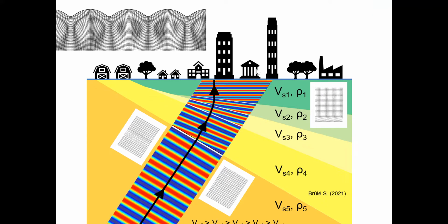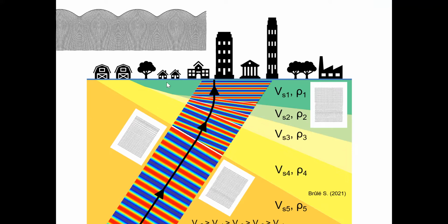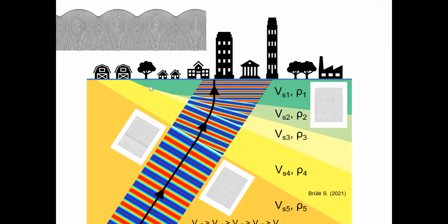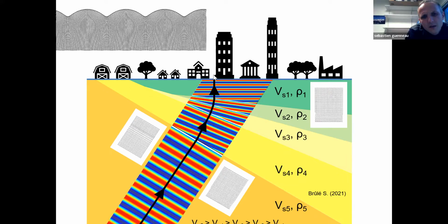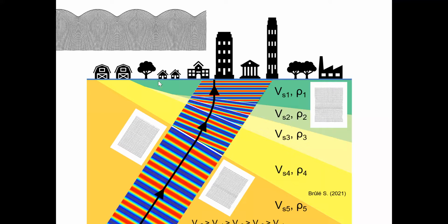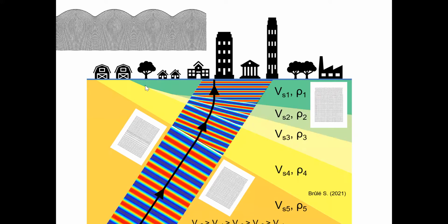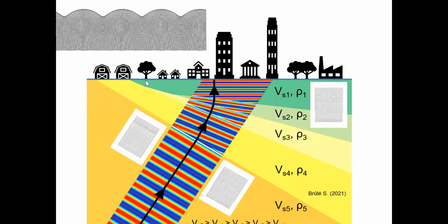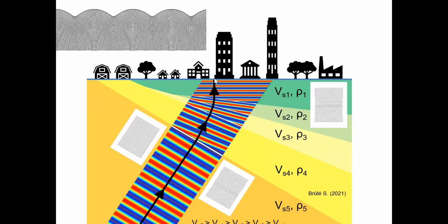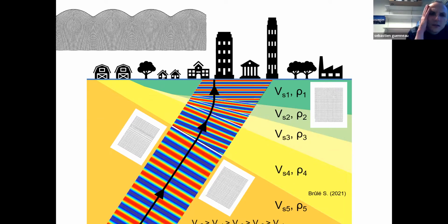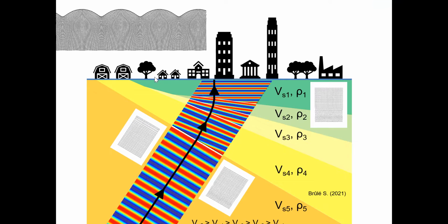Not only, because if the small building is on a small thickness of soil, it could be in phase for the resonance effect, because the frequency of the last soil here could be the same as the small one. So it could be in resonance due to the effect.